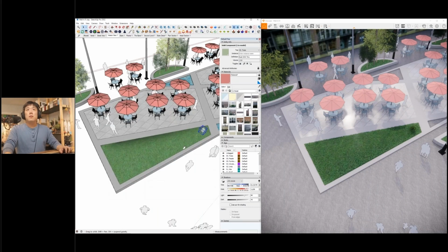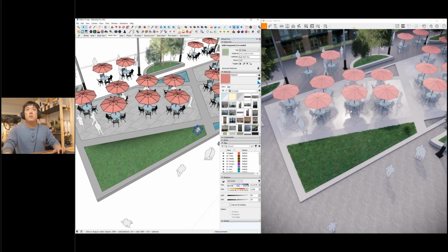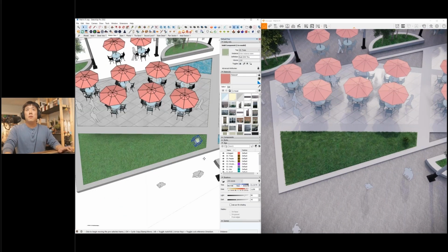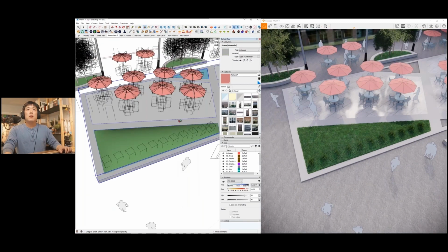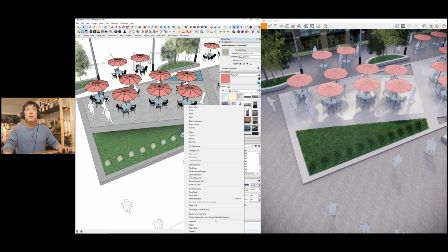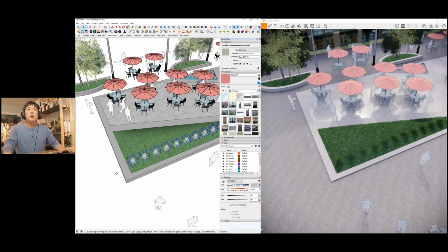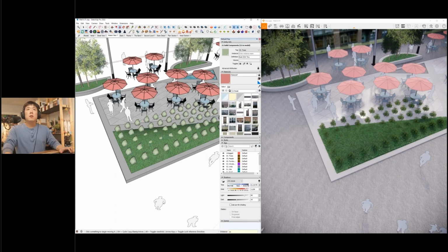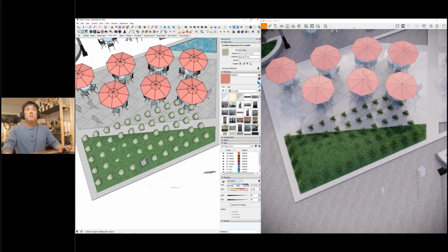Here, as I go through this, I can basically do the copy move, or move copy method, which is the array method inside of SketchUp. Then I park the next one here and type 10x, Enter. That will array the asset that many times. Then I select all of them again and array it this way, perhaps along the green axis, and repeat 4 times. I've got to clean up because they have now fallen off the edge.